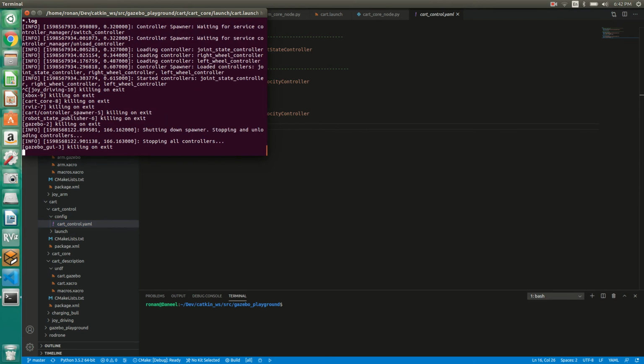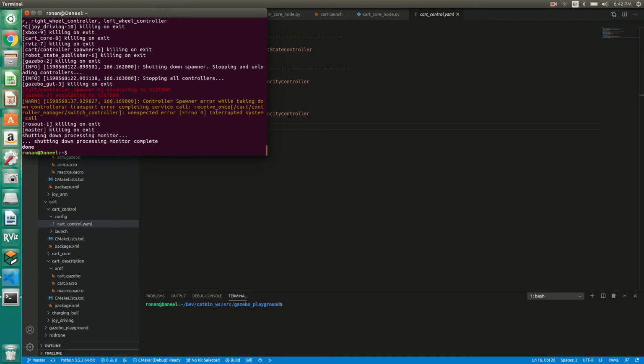So I'll close that up and then show the second demonstration, which is for the robot arm. And for the robot arm, it's exactly the same thing. I've specified a series of links specifying the arms of the robot, their dimensions, their moments of inertia, their mass, etc. And then I've specified 3 different effort controllers for the 3 different motors, which you'll see once I get them set up.